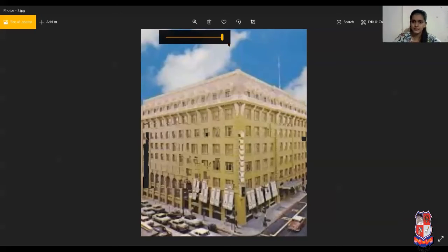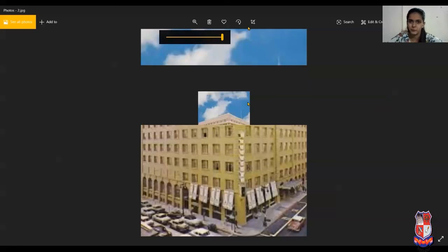Consider two sides, lengthwise and widthwise. You can see in both directions, and height is minor here, but considerable length and considerable width is there. So lengthwise projections and widthwise projections are going to meet at two different points. So this is an example of a 2-point perspective view.